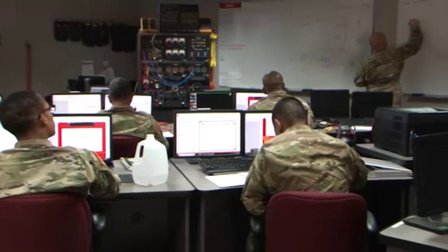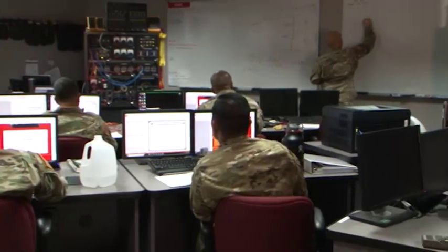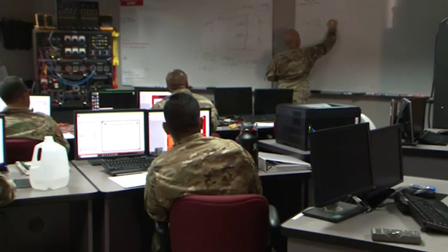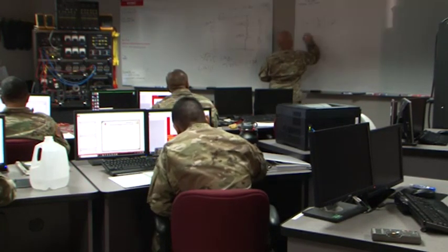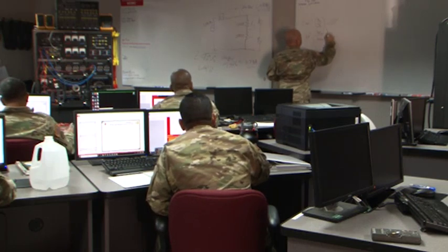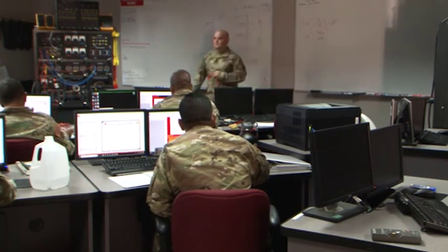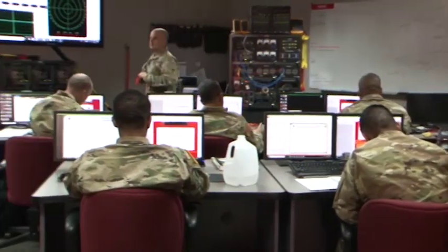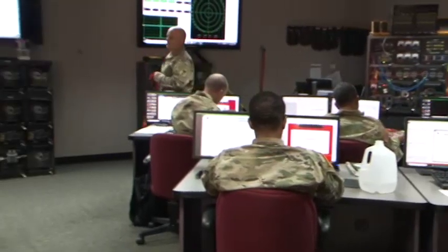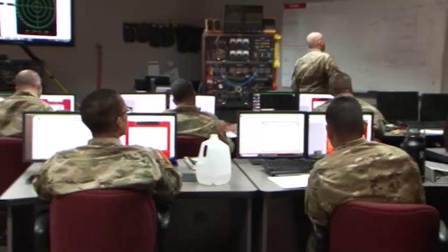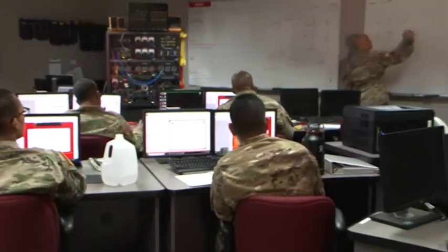So if tan negative 1 of X sub L over R equals theta, then I get tan negative 1 of 141 ohms over 100 ohms equals, is that what we got? What is it? 54.6.